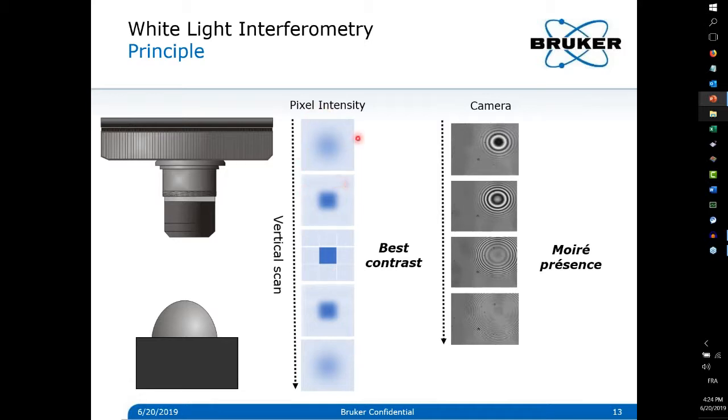The main difference is that focus variation uses a bright field objective and looks at adjacent pixels for the best contrast. The best contrast becomes the focal plane, and every pixel goes through these calculations in order to reconstruct a 3D map of Z height.